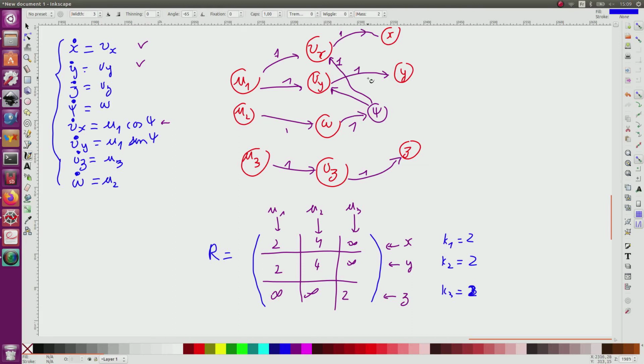So it will be a problem because the A matrix of the feedback linearization method will be structurally singular. It means that in the x and y derivation, the two inputs u1 and u2 should appear together. This is why I will have to delay u1 by adding two integrators. And if I do this, I will have a new input, let's say a1. This one will correspond to a2 and this one to a3. So they will not change.